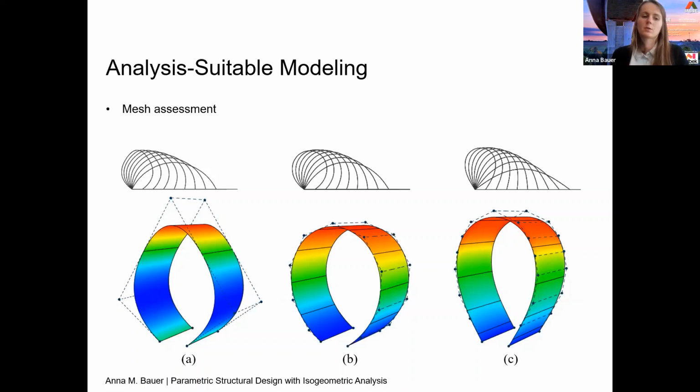So here for 5 control points in a row, we already see the result is just not good enough. And even if we apply more, we still need to check if there were already enough points. As the shape is always smooth, it's harder to predict if it's a good result. But we get a better result if the mesh was suitable. So it's important to add some degrees of freedom, do the refinement, and not forget it.